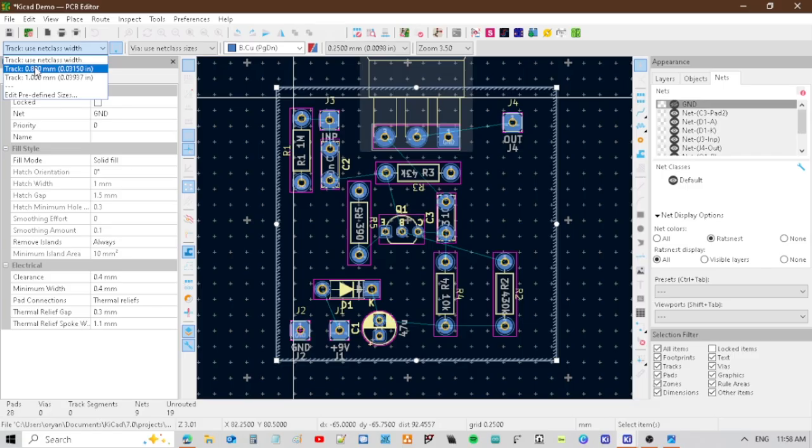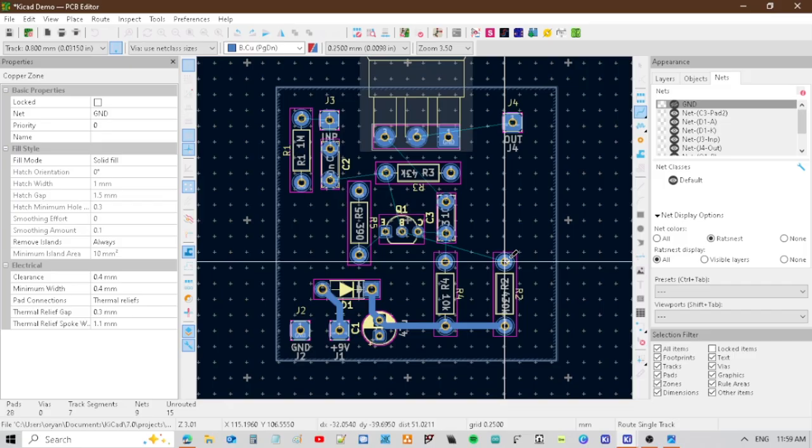Now if I click here, we're going to route our power. Go over the pad and press X. It's going to highlight the pad that it can be connected to. We're going to do that. This is all power, and once you've hit X once, you're in this mode and you can just keep clicking things. That's done. We're going to switch to our 0.8 because that's all the power being distributed. We're going to go under this resistor. It kind of wants to jump everywhere, so you're going to do this in steps. Get it to go the way you want and click, then keep going and click.